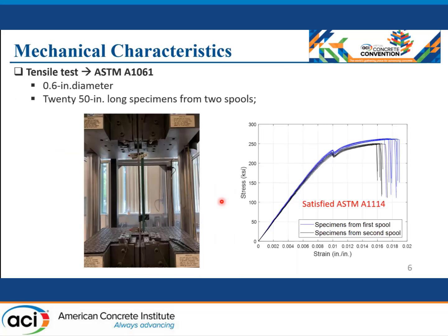So to determine the stress-strain curve, we tested multiple 0.6-inch diameter stainless steel strands from 2 spools in tension following ASTM A1114, and those are the stress-strain curves. All the tested strands satisfied the ASTM A1114 requirements.